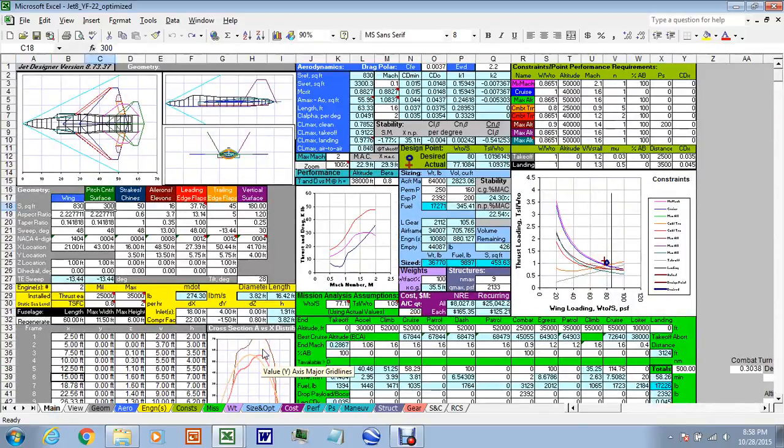But is that really true? Is that what happened on the real F-22? Well, speaking with the folks who designed that airplane, they said yes. The aircraft exhibited this same phenomenon where d epsilon d alpha was approximately 1 at the position of the horizontal tail, so the horizontal tail didn't contribute to longitudinal stability.